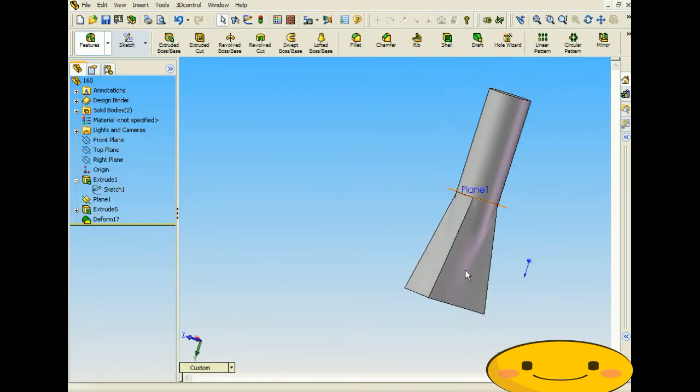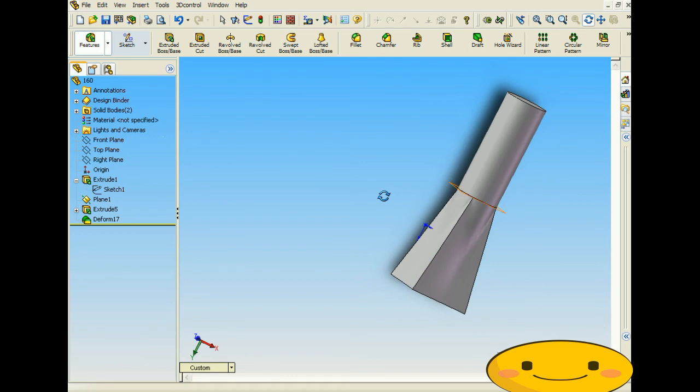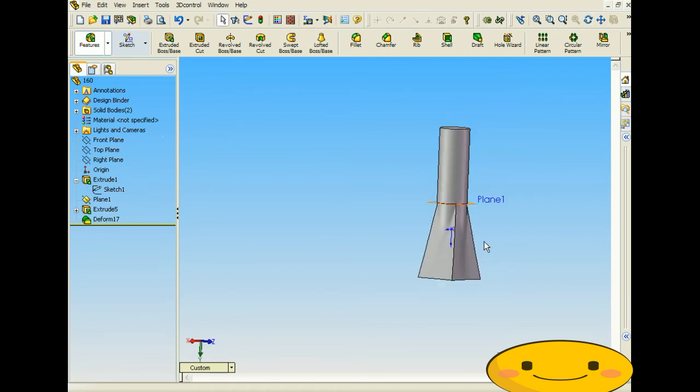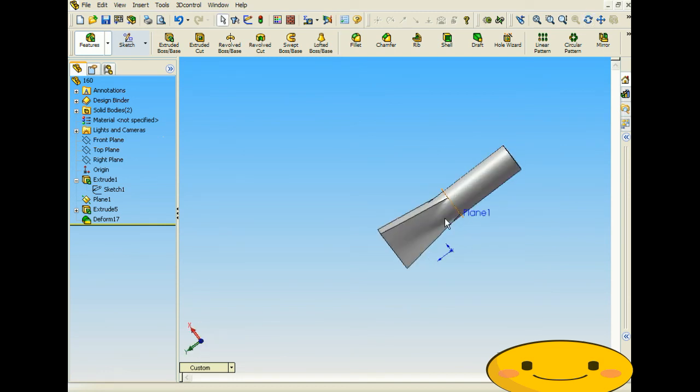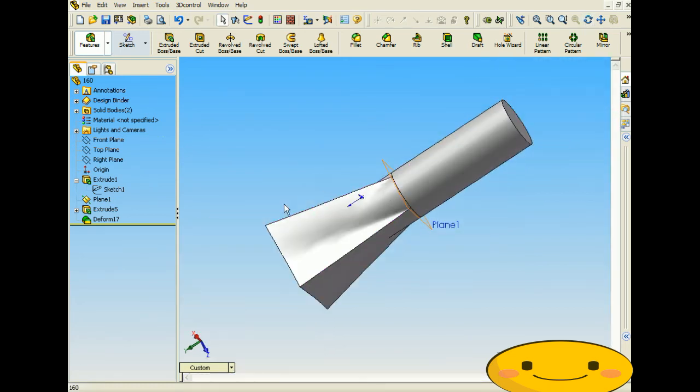Now if we wanted to do this without using the deform feature, it would be very, very difficult, and we probably wouldn't get the same result merging the two together. So the deform curve to curve, it's used when you want to kind of bring two objects together, so you get kind of like a blend. So if you have, like how we had the cube on this side and the cylinder on this side, you're kind of bringing the two objects together, blending them and making them one.